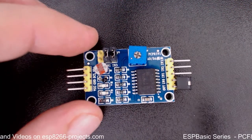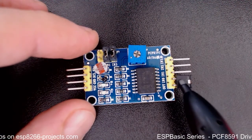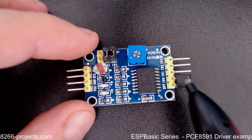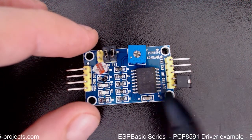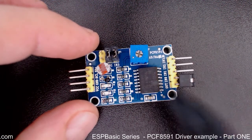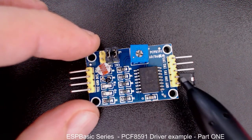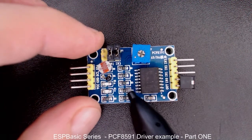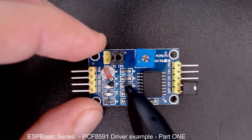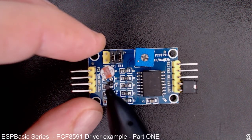Also remember from last time the problem that we had related with the DAC output, especially on the higher interval. After 2.8 volts we start having problems, and we found out that it was related with the fact that this LED is connected directly to the DAC output. So don't forget to remove this resistor from here if you want to use it for anything else than playing with this LED.